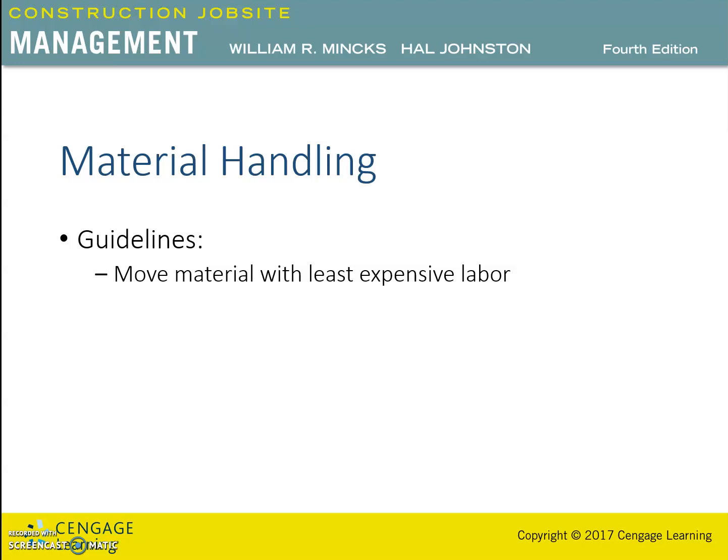Normally, the lowest paid members of the crew, such as laborer, apprentice, or helper, should be responsible for moving material. The craftsperson, such as a carpenter, is paid a higher wage to do a specific type of work, so crews should be organized to avoid using the craftsmen for moving material.